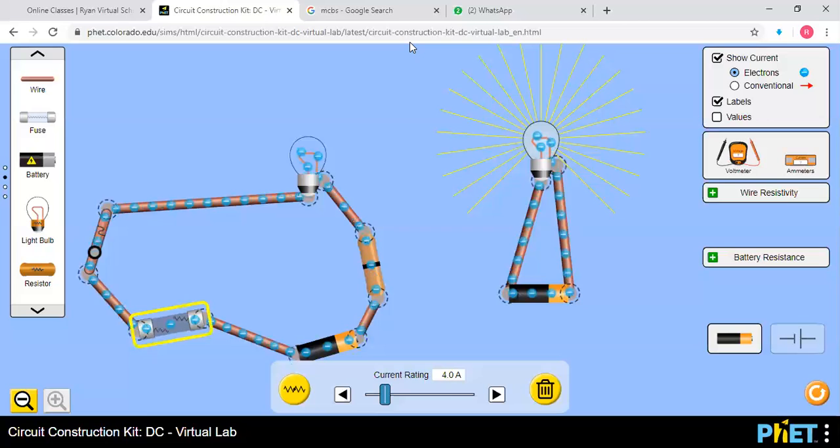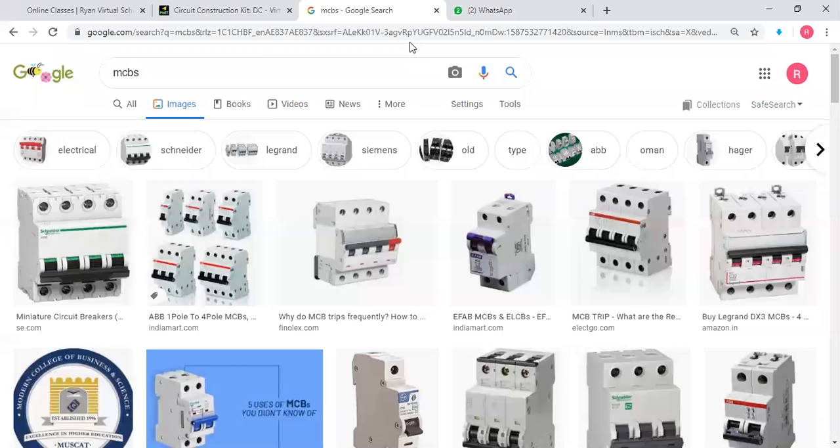And in the home, along with the fuse, what you can see on the board are these MCBs. What this does is similar to what a fuse is doing. All your main appliances will be connected to this directly, so that if any current more than the requirement is passing through it, suddenly this will go off. We might have seen so many times, going to the board and switching it off because suddenly